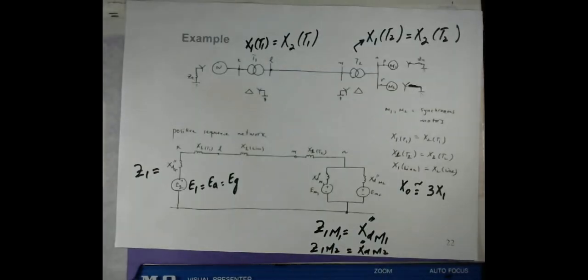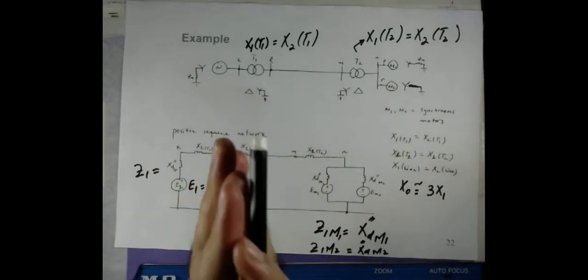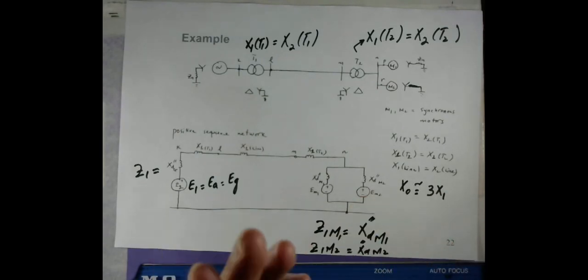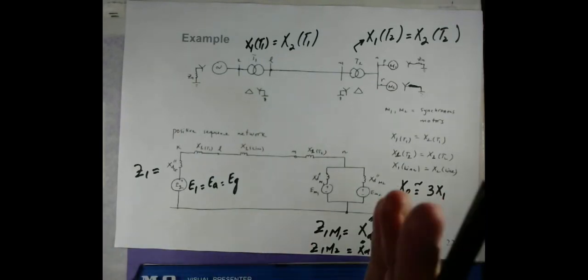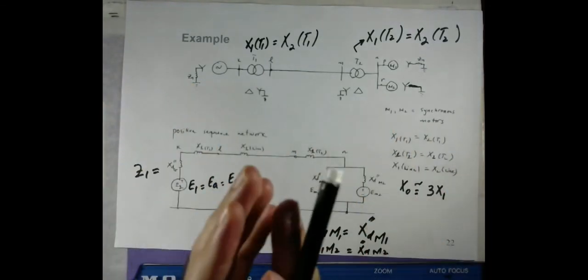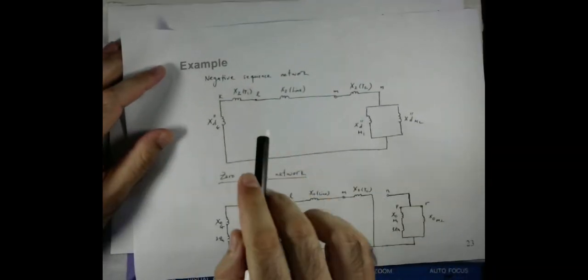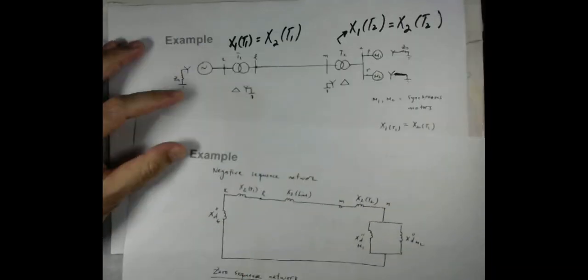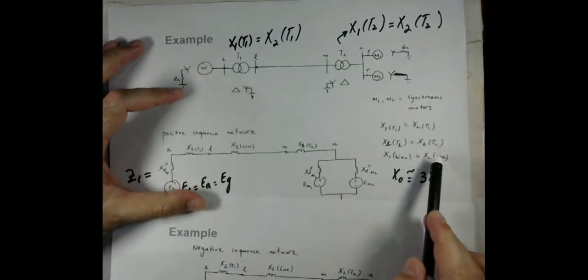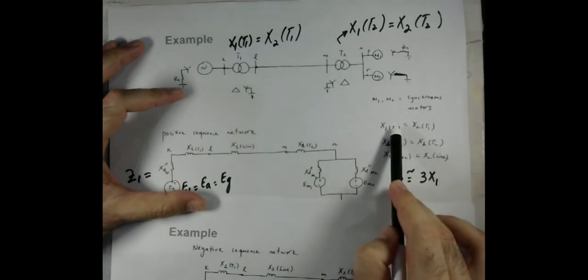So now accounting for these two facts, where in the negative sequence network we do not have a voltage source, and also considering the negative sequence reactance is still for the synchronous machines the subtransient inductive reactance, the network can be drawn like that, because transmission lines have the positive and negative sequence inductive reactances the same, and also for the case of the transformer.